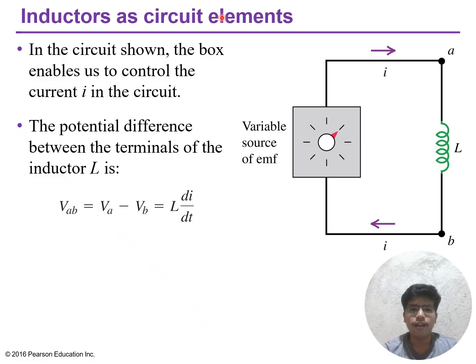So we have V sub L equals L di over dt, not depending on the current magnitude itself, like V is equal to IR. If the current is constant, or di over dt is equal to 0, the inductor acts like a short circuit. If the current changes rapidly, even a small current can produce a large voltage. This contrasts with resistors, where voltage increases directly with current.